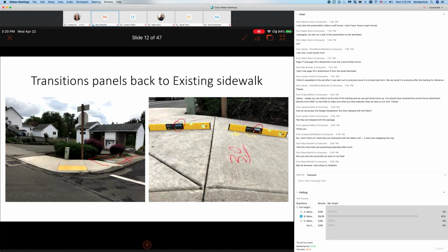And I'm not sure if this means a 3% in this direction. If this is the slope here coming into the ramp, here should be 2%. So the transition should be 0.5% per foot. So if this here is 3%, that's definitely also failing, warping too fast.